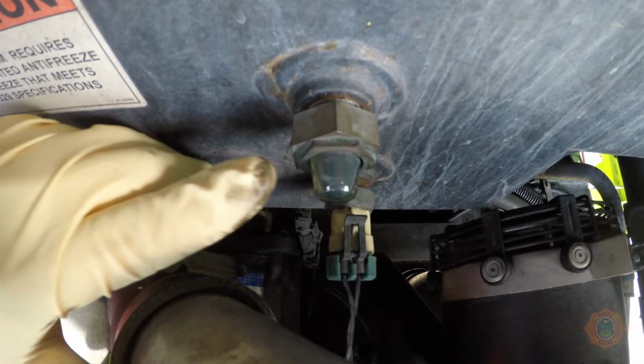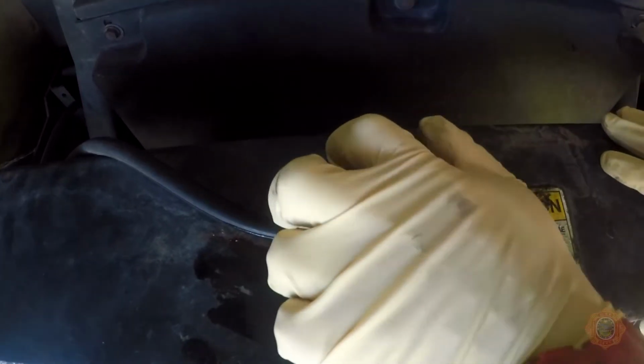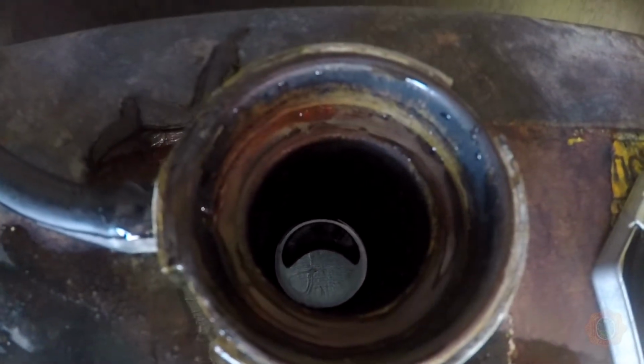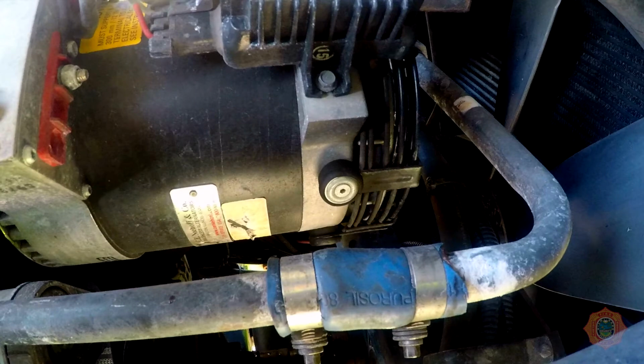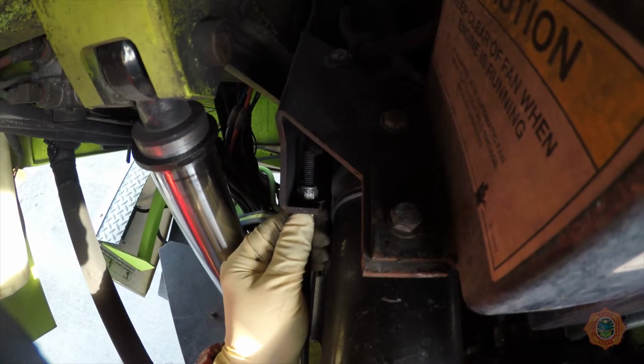Check coolant levels when the engine and radiator system are cool. Remove the cap on the antifreeze fill port or look through the sight glass. Determine whether the antifreeze is at the proper level and mark inside the reservoir. Check the radiator hoses, fluid leaks of upper tank, and inspect the radiator mount.